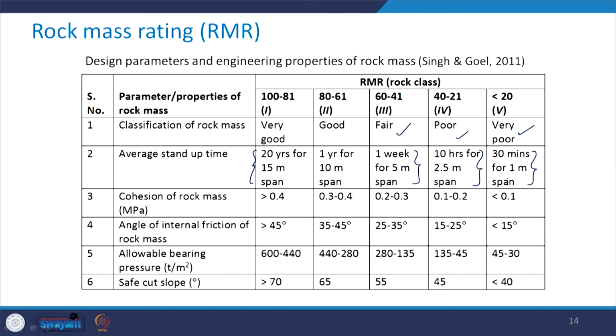So although here you have 10 hours for this 2.5 meter span, you should not wait till 9 hours and then only go for the installation of the support system, because in those 9 hours the rock mass quality after excavation will deteriorate, and ultimately the effective average stand up time may not be this 10 hours for 2.5 meter span. So, we have to be careful about this.